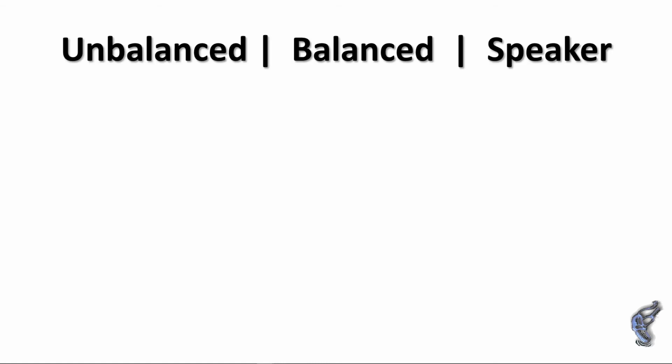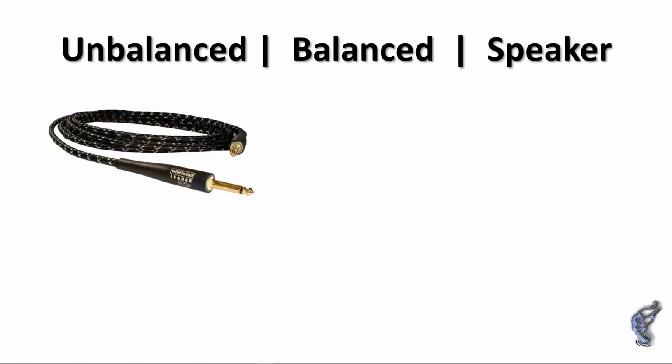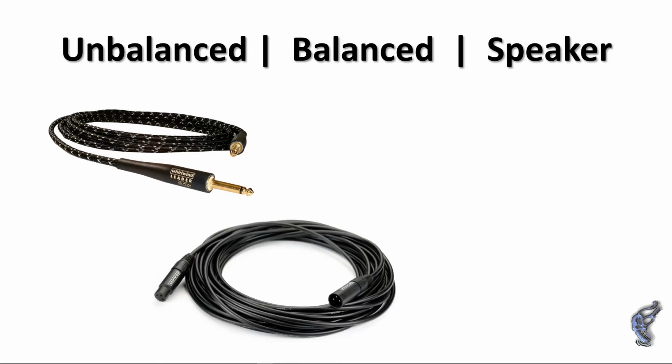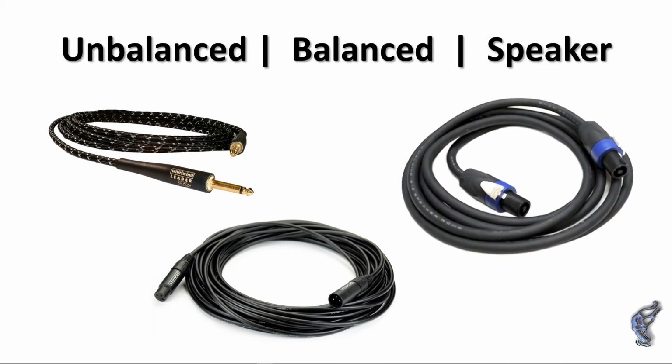To summarize, we use unbalanced cables to connect guitars and keyboards and even CD players to our sound system. We use balanced cables to connect the microphones to the console and to connect the console to the power amp. And then we use speaker cables to connect the power amp to the loudspeakers.